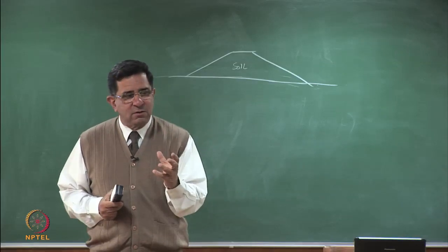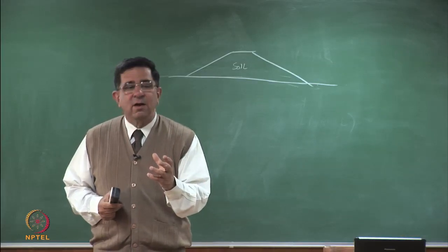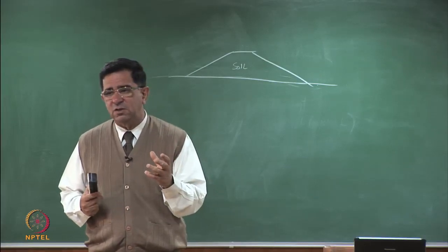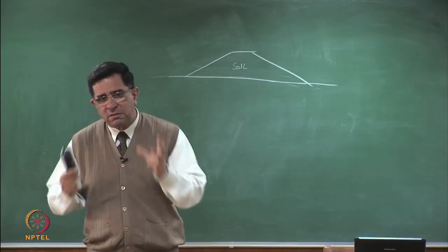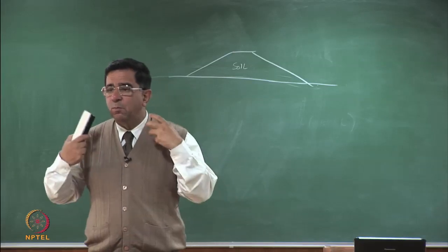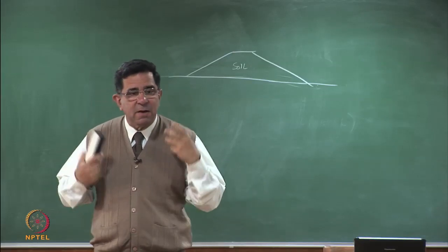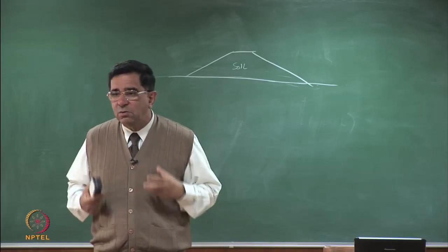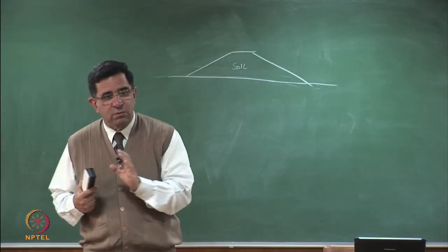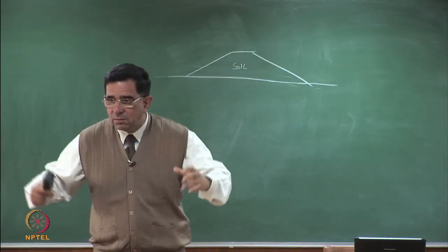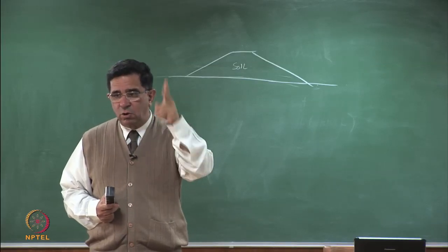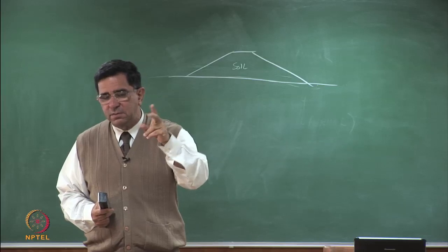It's like if you have 10 particles of gravel in sand, or 10% gravel in sand, will it make a lot of difference to the angle of shearing resistance of sand? If the particles float amongst the sand particles, they are not coming in touch with each other. So only when the portion of gravel becomes significant, 25% or more, do you start to have an effect of the coarser material. So sometimes you can even remove the coarser material so that you are able to do the test within the limit. So use a large direct shear box, do a slow test to get drained parameters.